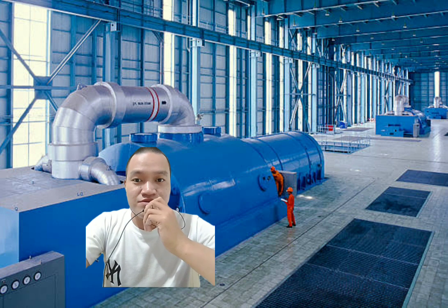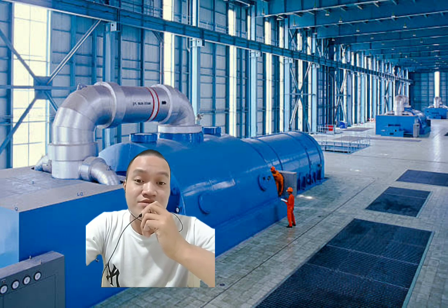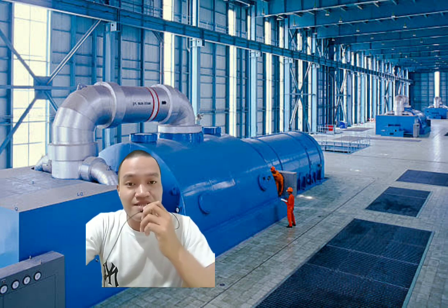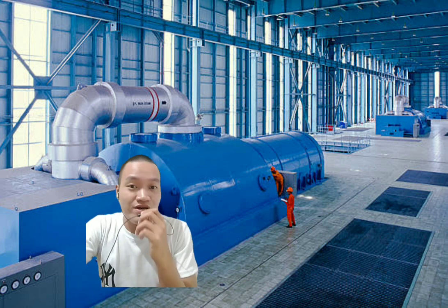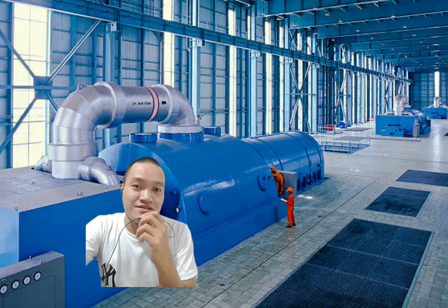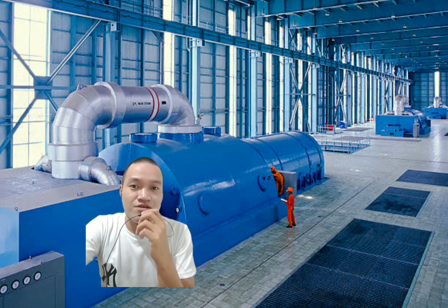Next operating procedure is the full away. So the maneuvering revolutions are usually about 80% of the full away or the full speed condition. So the turbine can be gradually brought up to full power operation once the full away command is received. The process takes 1 to 2 hours. So it's very long.